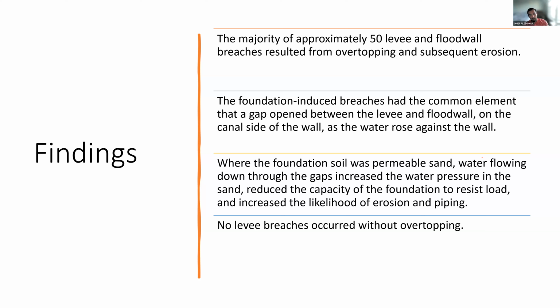The new design after Hurricane Katrina is that they design the levees to be overtopped. Either they put a seepage berm on the protected side, or they add T-walls with battered piles going 100 or 120 feet down, so it can overtop and stay stable. Even the erosion will not flip the T-wall.